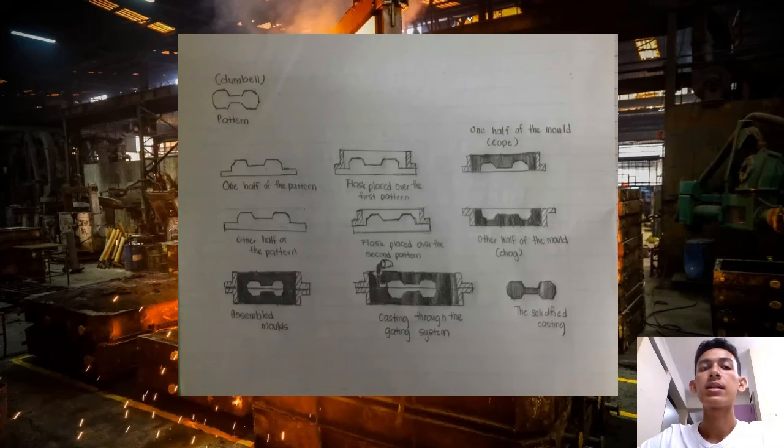The last part is cleaning step. So this cleaning includes removing the gating system and runners, as well as any residual molds or core parts that remain in the final pieces. The part is trimmed in areas of excess, and the surface of the casting can be sanded or polished to desired finish. After cleaning, each part is inspected for defects and is tested to ensure compliance with the manufacturer's standards of quality, so that they will perform as intended in their respective applications, so that it can have a dumbbell shape perfectly. That's all from us.